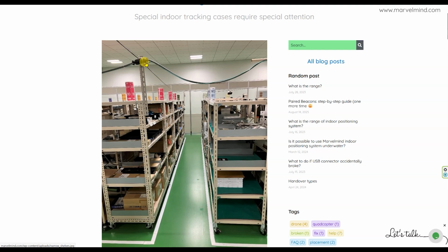So it means that if you typically install one station beacon here and another there, the ratio of the width to the length will be too small. So it means that the width is too small as compared to the length. So effectively, and if you combine it with the height, it makes the trilateration even more problematic. And as a result, instead of 2D tracking, you have 1D tracking.